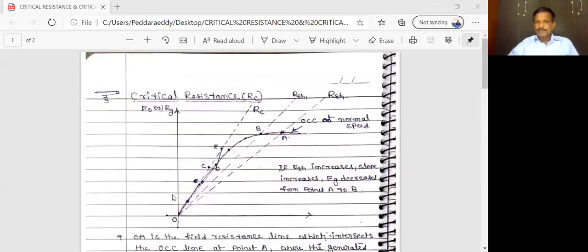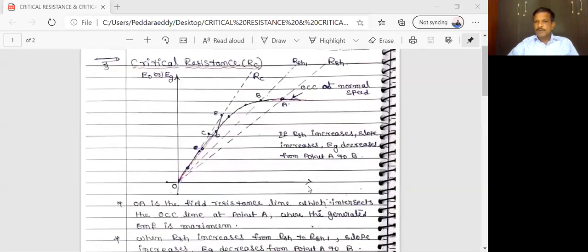So this is the diagram. So this is x-axis and this is y-axis. We are taking on x-axis field current IF and on y-axis generated EMF EG. Okay, and based on previous discussion on how the voltage builds up in a DC generator, in that discussion we saw how the EMF is generated step by step or cumulatively. So when we add all points, we get open circuit characteristic curve.